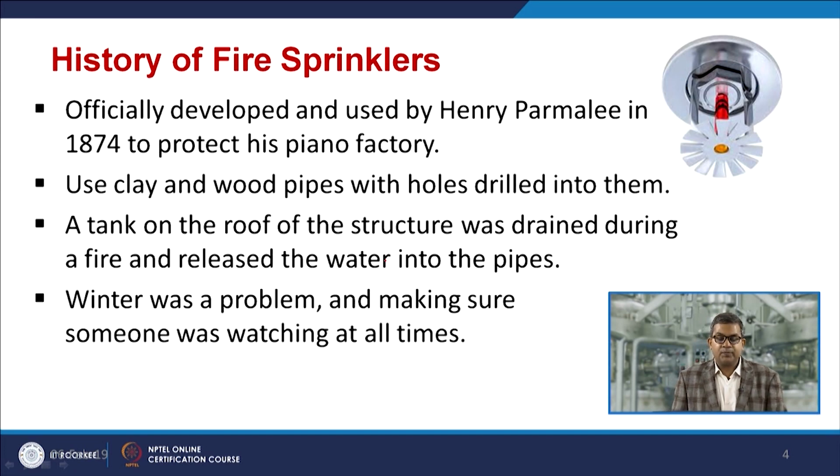It was officially developed and used by Henry Parmelee in 1874 to protect his piano factory, because he used to manufacture pianos with wood and there was a prominent chance of catching fire. He used clay and wood pipe with holes drilled into them, and a tank on the roof of the structure was drained during a fire and released water into the pipe. Winter was a problem, and it was necessary to make sure someone was watching at all times.